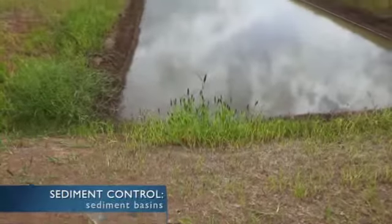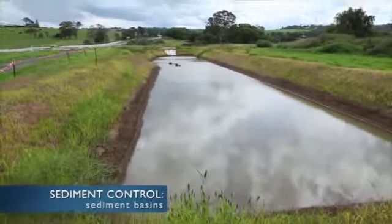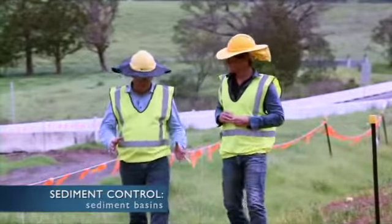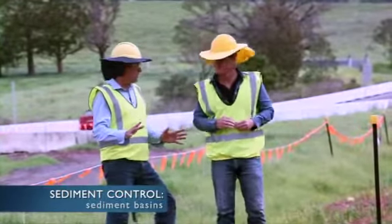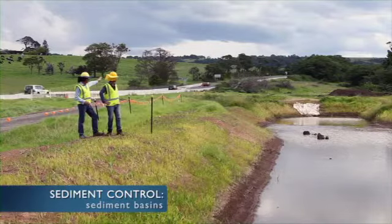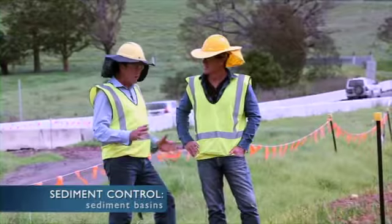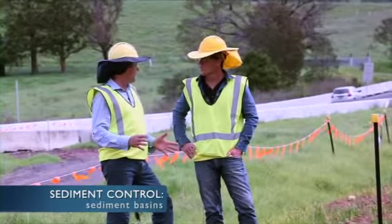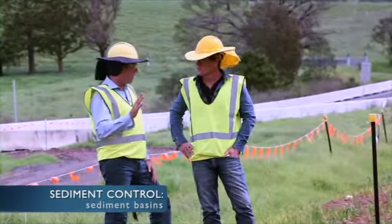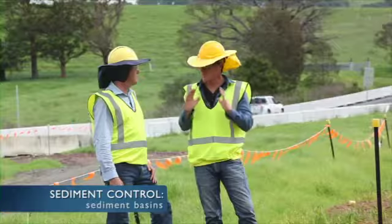And here's a great example, Chris. It's in early before the major road construction starts. Yeah, that's right, Pete. So as we said before, it's really important for us that the controls get in there early. As you can see here, they haven't started clearing that hillside yet, and as soon as they do, we know we're going to get erosion off there. So it's really a matter of the whole project team working together to work out a way to get these controls in place before they're getting into the major construction work. At the planning stage. That's right.